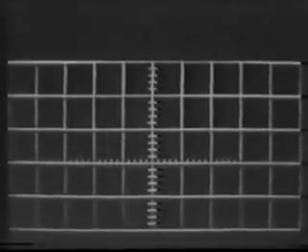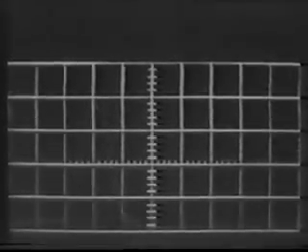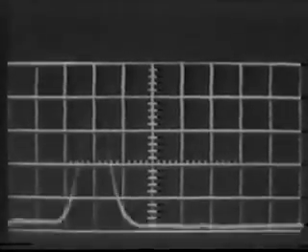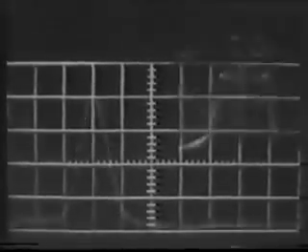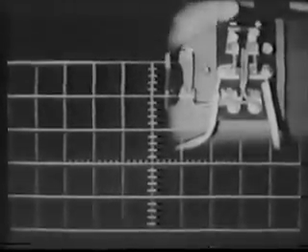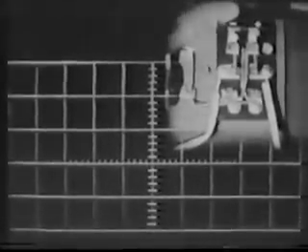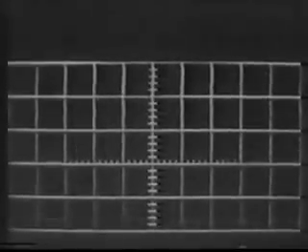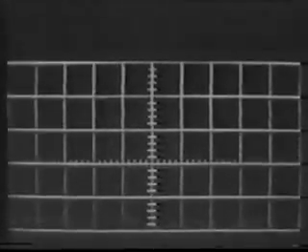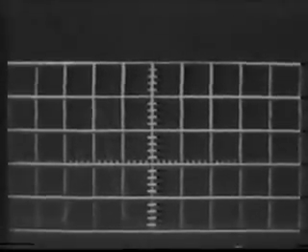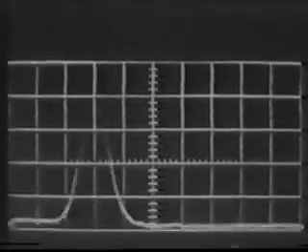Third, the disturbance which drifts down the bar moves like a positive charge, as we believe it should. The electrical field is now directed from the source toward the detector. And if we remove the field, there is no pulse. And finally, if we reverse the field, there is still no pulse. So only when the electrical field is directed from the source to the detector do we see a delayed pulse. Since we believe we are producing electron-hole pairs with our light source, the detector must be collecting positive holes which drift down the bar under the influence of the electrical field.